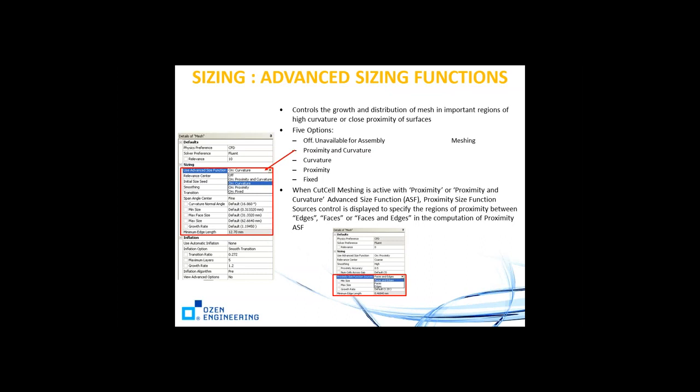And then this feature here, use advanced size function. I really like this feature, because advanced size function plays a very important role if you have curvatures in your model. Like if you're doing a CFD problem, a shower head problem with a bunch of tiny features, then you should come here and turn on the advanced size function option to curvature.